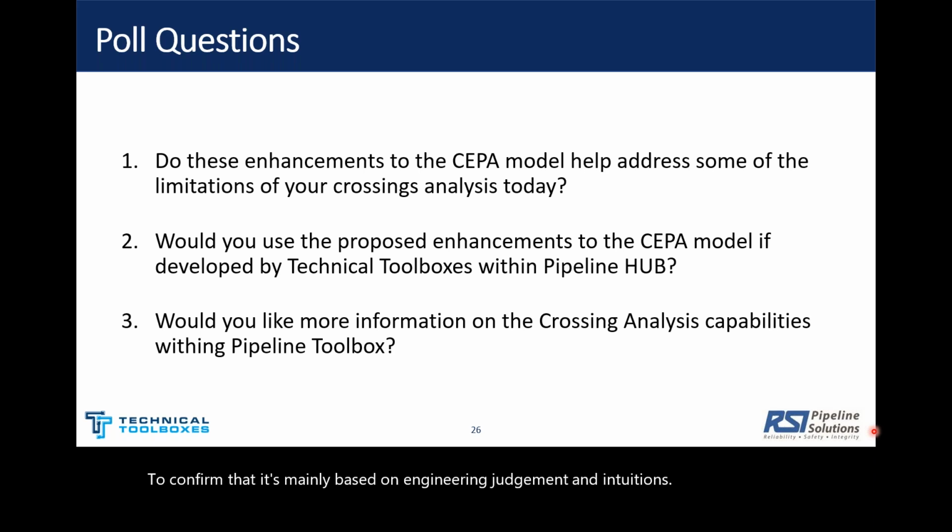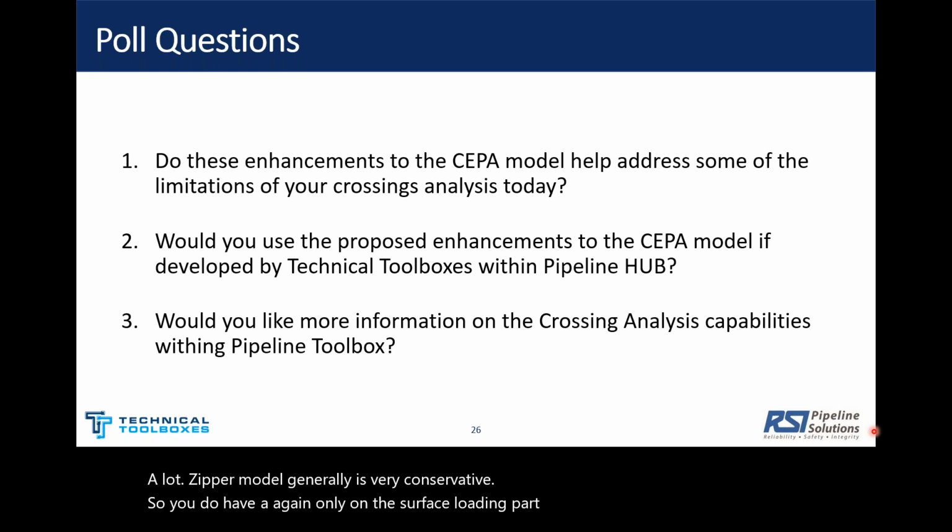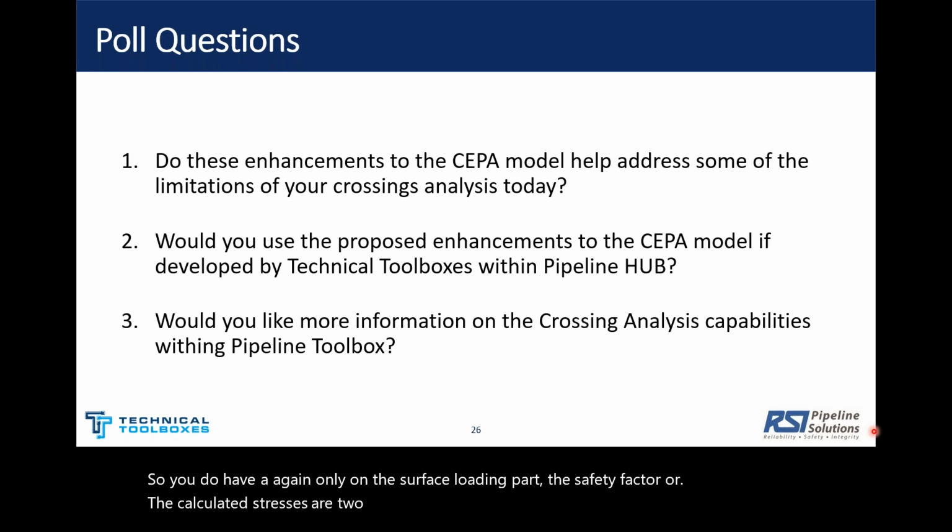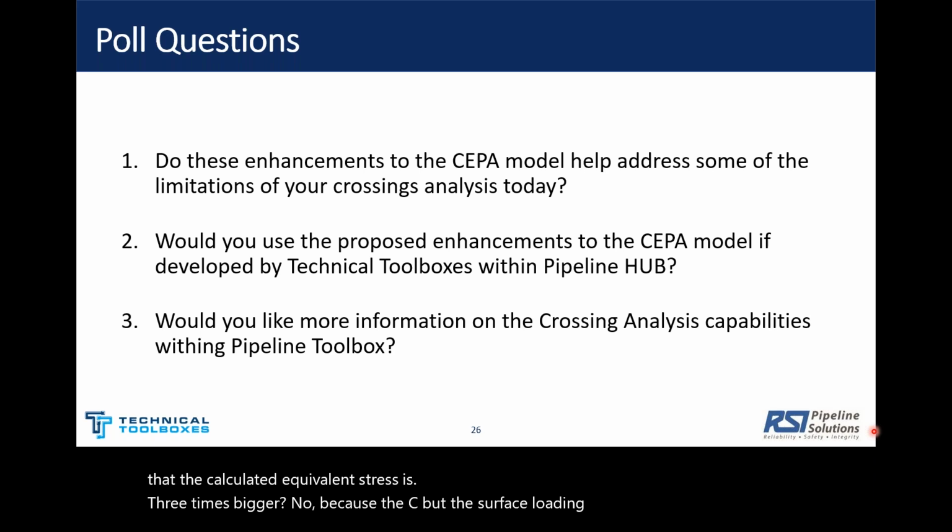Okay, general question: how much conservatism is built into the CEPA model? A lot. The CEPA model generally is very conservative, again only on the surface loading part. The calculated stresses are 2 to 3 times bigger than the actual stress. It doesn't mean that the calculated equivalent stress is 3 times bigger. No, because the CEPA surface loading induced stress is only a part of your total stresses, right?